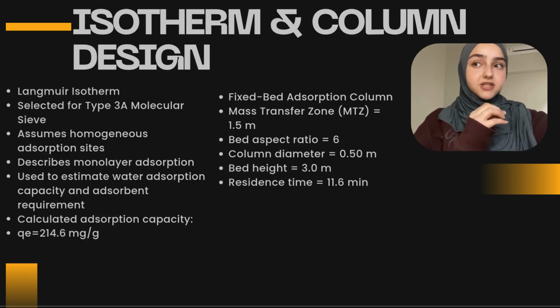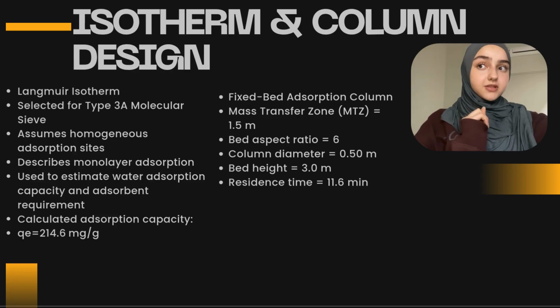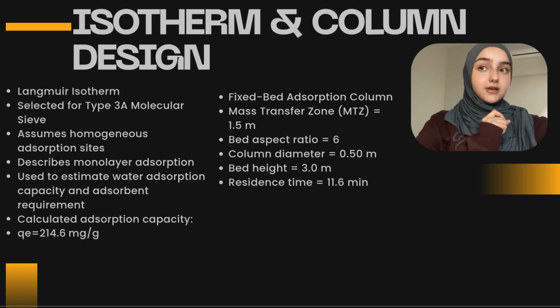For this design, we selected the Langmuir isotherm because it accurately represents the adsorption behavior of the type 3A molecular sieve, which has uniform adsorption sites. Using the Langmuir model, the adsorption capacity was calculated to be 214.6 milligram per gram. At the end, we designed a fixed bed adsorption column with an MTZ of 1.5 meters, a diameter of 0.5 meters, and bed height of 3 meters. The calculated residence time of 11.6 minutes provides sufficient contact time for efficient removal.